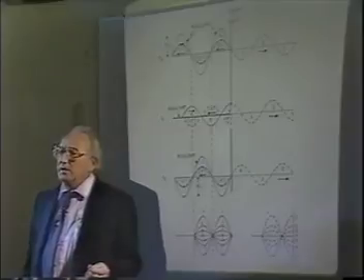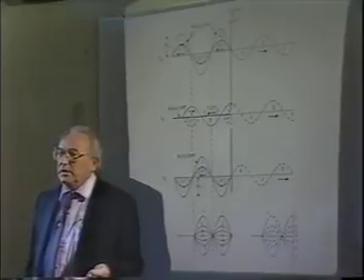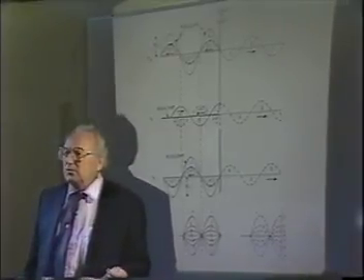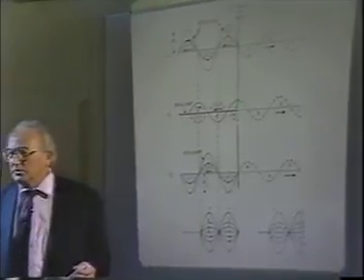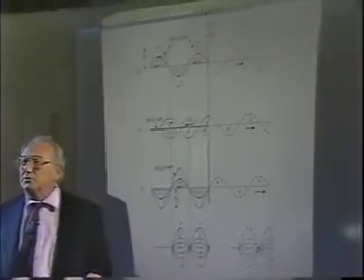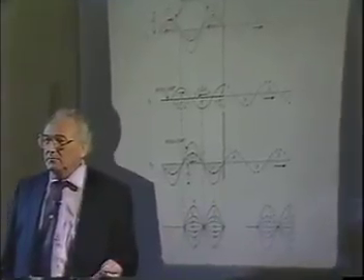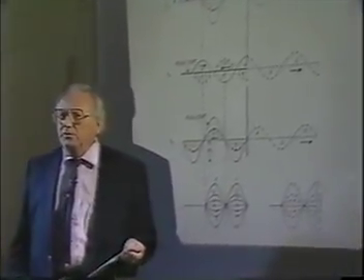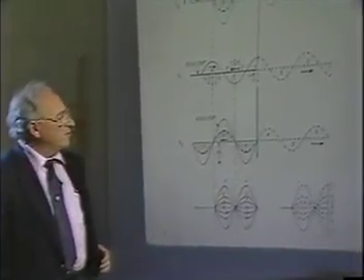That's the way you develop standing waves. To get these two signals, usually it's going to be because of a reflection. However, there are situations where you have leakage signals in the system. It looks exactly like a reflection, and you'll have the same effects in the overall system.